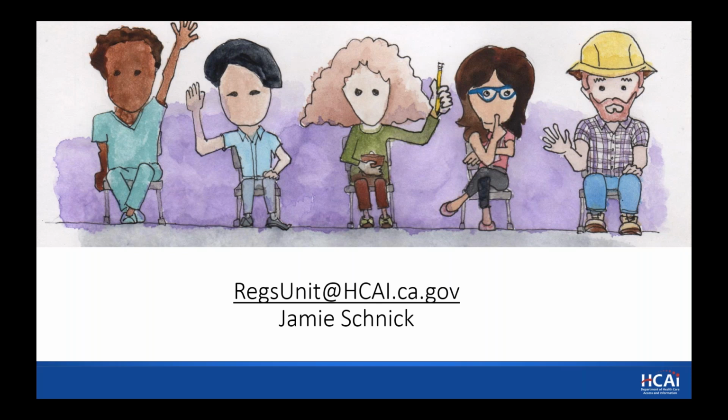Awesome. Thank you, Jamie. Next question reads, does the transformer have dedicated space requirement on top? No, it just needs ventilation space requirements. Thank you. Next question, is GFI switch allowed to protect the receptacle serving equipment? A GFCI switch? Yes, absolutely. That's what I was talking about, where you pull out the GFCI device separate from the receptacle. Right. Thank you.